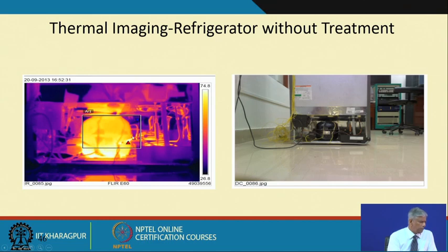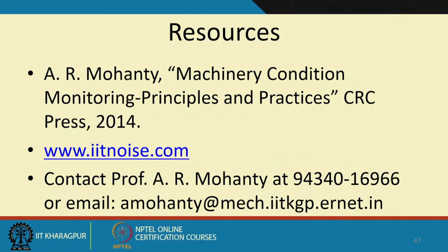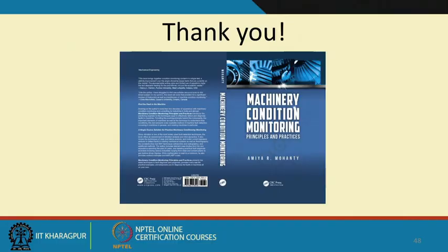So, you can very easily measure the temperature of the compressor, okay, and all the conductors by using a thermal imaging. So, these are some of the applications of thermography for finding out quick ways to find out faults, and more of this you will find in my book.